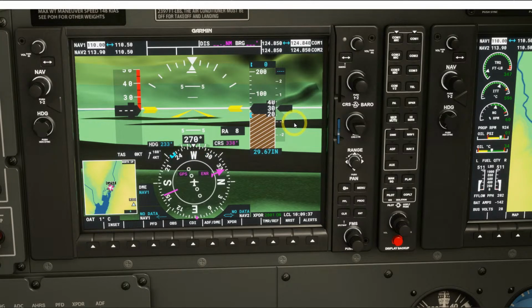On this aircraft, when you select, if you climb at 500 feet or 800 feet or 1,000 feet per minute, this black triangle here will move up or down if you are descending, and it will set itself at the speed that you are climbing. So if I'm climbing at 1,500 feet, it will show here 1,500 feet and it will move up to here. It will stay there. And if I start descending at that point to, let's say, minus 1,000 feet per minute, it will show 900, 800, 500, 0, minus 500, and minus 1,000, and it moves to here. So this triangle moves up and down.